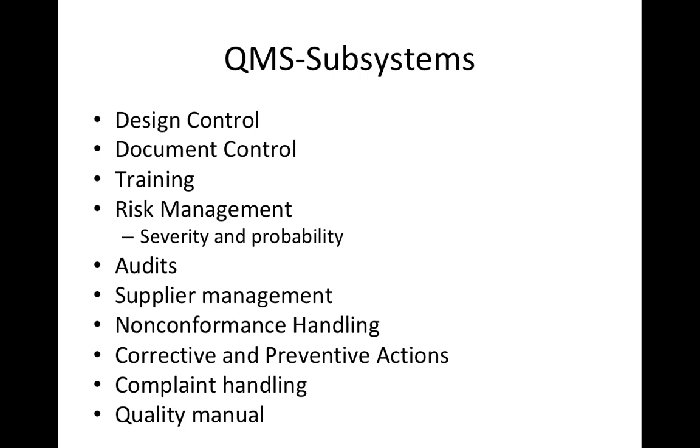The next thing you want to do is what's called a preventative action. So the preventative action is, how are you going to prevent this mistake from happening again, right? If you overheated that plastic and that's what caused the problem, how are you going to prevent that overheating from happening again? One of the things you might do is set a limiter on the machine that's heating the plastic. So if it's not supposed to go over 100 degrees Celsius, you set a limit saying 100 degrees Celsius is the maximum. Any sort of personnel cannot go any higher than that. So it prevents it from being overheated in the future, so you don't have that same error, right?